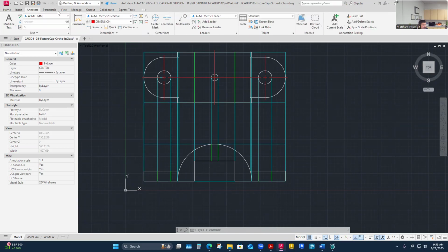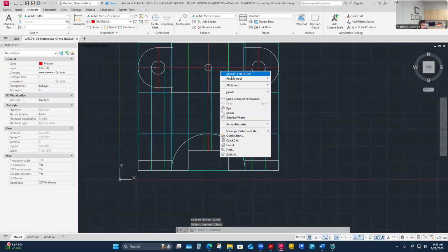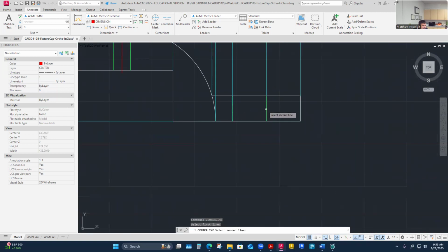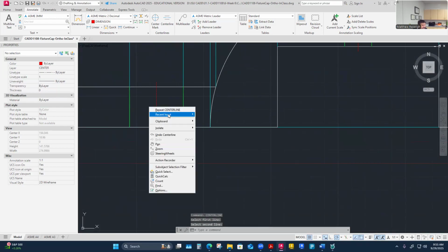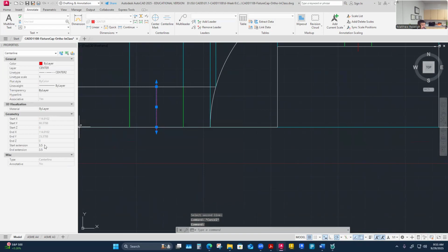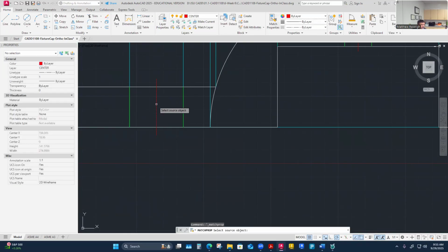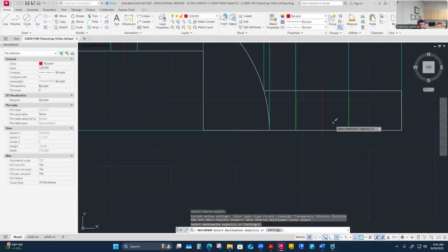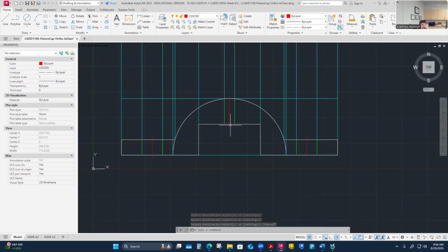So you show it, yes, but you dimension it so that nobody can misinterpret. I do want to put in these center lines here though. So I'm just doing the center line and then choosing these hidden lines. I'll do those. And then I'll change one and match its properties, but they're there right here. I'll change 1 to 6, and then I'll match those properties. And I could argue that if I'm going to dimension, this center line might become extended beyond where it is as I go to dimension